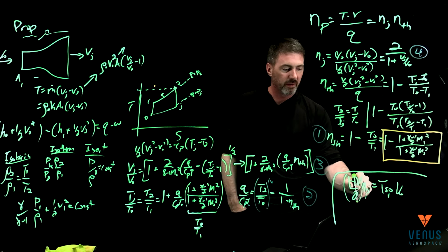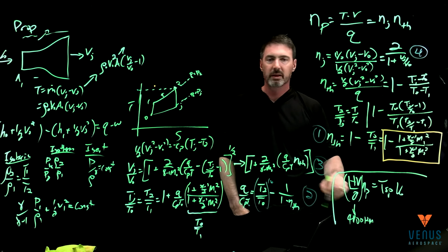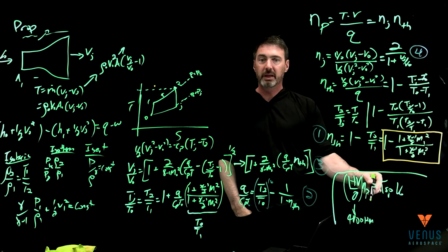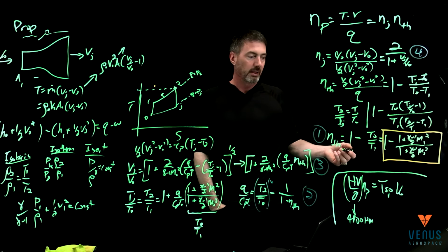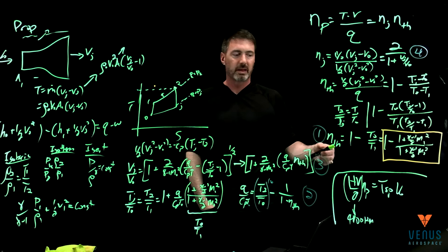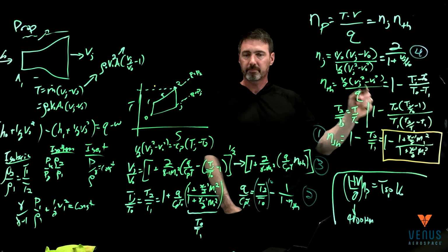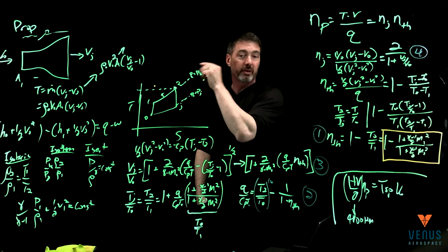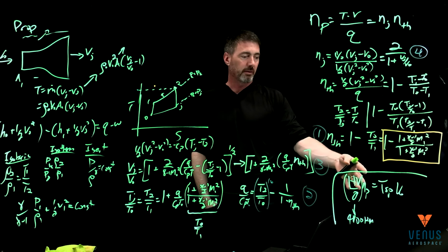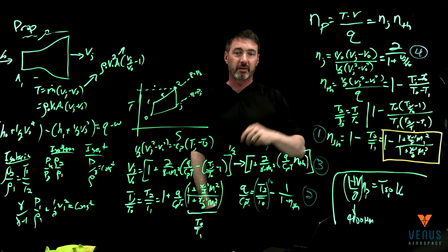Again, the heating value divided by g for kerosene is 4,400 kilometers. It's a great unit. It's 12,000 for hydrogen, but we've shown how hydrogen is pretty horrible. And so if you're looking to solve for your Isp, you actually already have it. If you wanted to do anything else, you could just add a knockdown efficiency on top of all this. But basically, everything falls out by setting the speed you're flying at and your maximum temperature that you're willing to accept within your ramjet system, and you're done. You actually have your full propulsion efficiency, and then you can look at things like range and Isp, and all those things fall out of all of this.